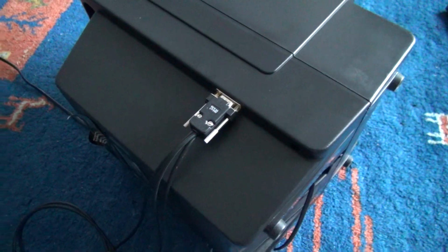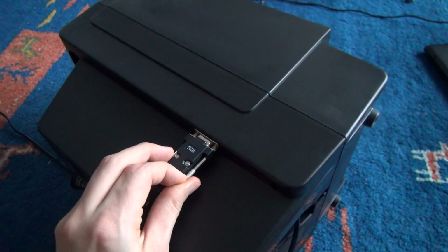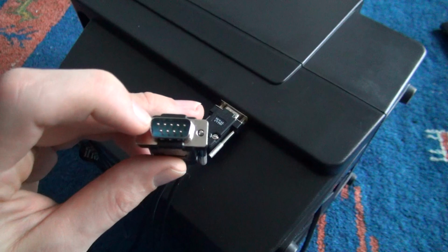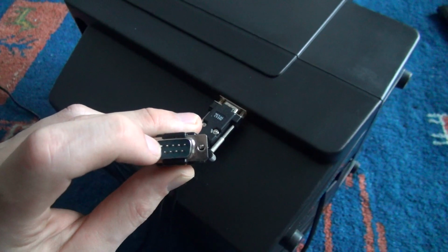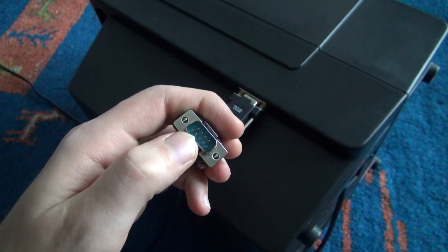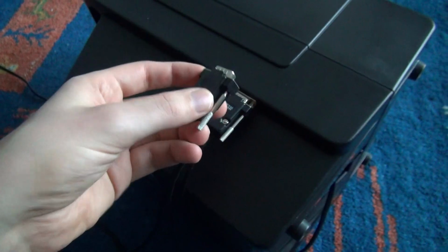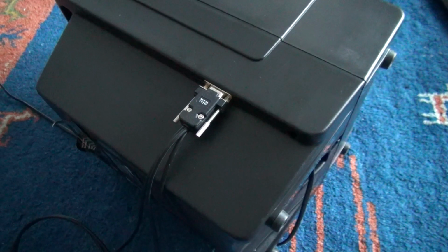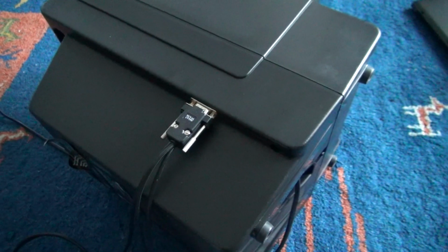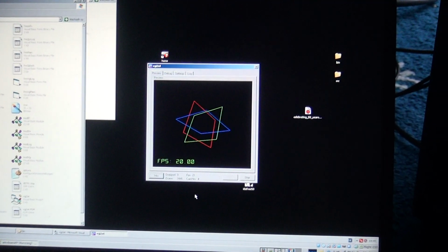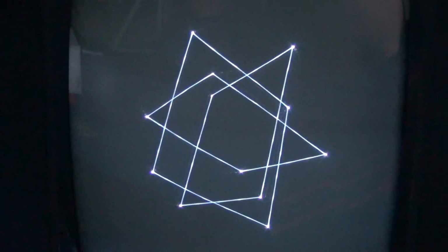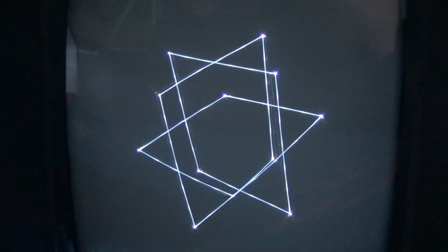And the trick here is quite simple. I have this plug here, and when I remove it, I can exchange it with a blind plug basically. So I have it here. And this shortens out the connections between here, and on the one row I have the outputs from the Vectrex board, and on the other row I have the inputs of the amplifier. So that gets short-circuited then, and then if I plug this in, I have my normal Vectrex console back and can play the games from the cartridges, or I can input this and access the vector amplifier directly. So here I have the star demo running, and I hooked up my Vectrex to the EasyLace, and that's what's coming out. I get a nice vector graphics image. And yeah, I think now it's time to have a look at the laser projector and see how VGI performs there.